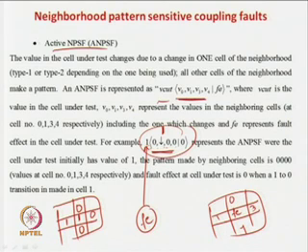Now what is the fault? There is a drop in this one, so this one changes to 0. If you do this, this cell also gets affected and it gets converted to 0. Now why is that? Near about everything is 1, now it is 0, so all of them together pull it down to 0. But initially it was not 0, because this cell was also a 1 and that was helping it to be a 1. Now if you make this one a 0 for some reason, then being surrounded by all the other zeros it changes to 0. So because of this activity from 1 to 0 in this one, this gets 0.